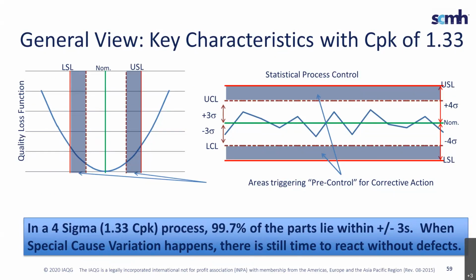Identifying key characteristics is so that later in the process control, we understand where reducing variation adds value. That's very important. Controlling it to the spec limits is no longer good enough. Okay, that is good enough to meet what the customer is paying for, but it's not good enough to make the customer enthusiastic. What we need to do then is control the variation and reduce variation toward the center.